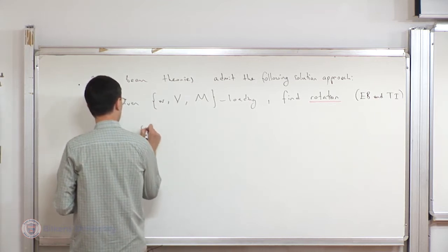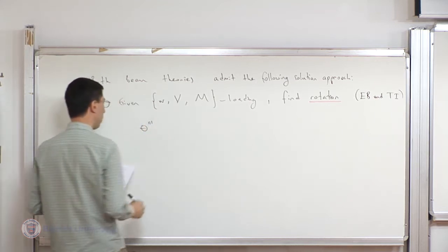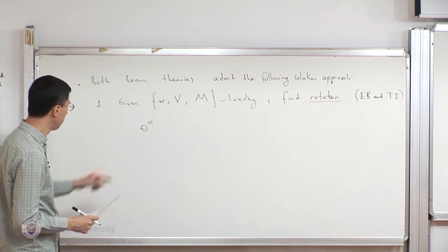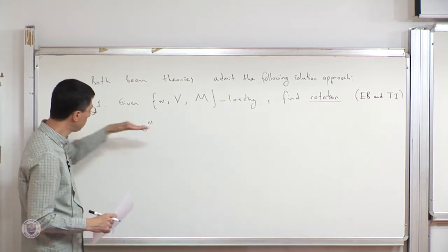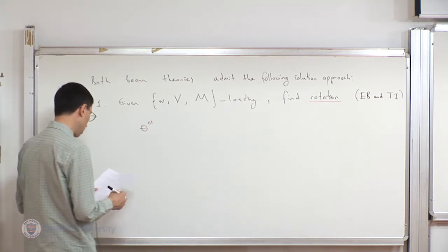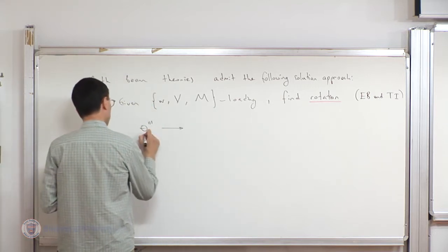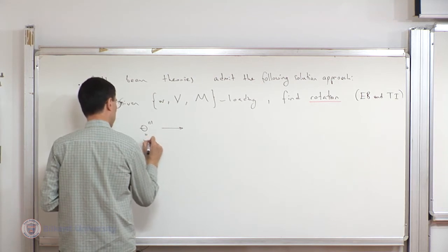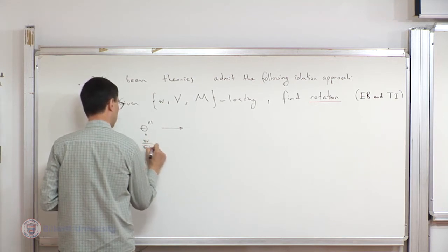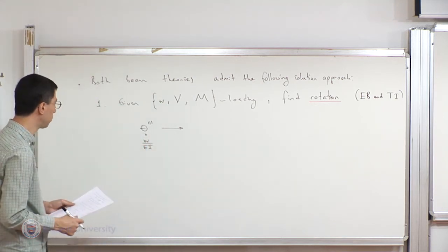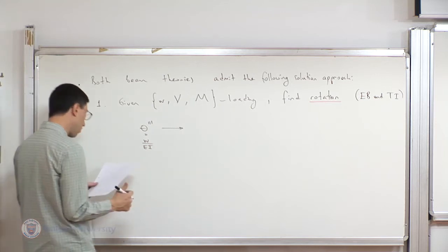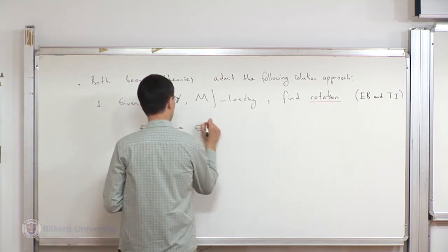And the way we work is we start from the third derivative. Derivative, remember, is with respect to x1, the horizontal position. Third derivative of the rotation. And we know that the third derivative of the rotation is the distributed load divided by Young's modulus times moment of inertia.